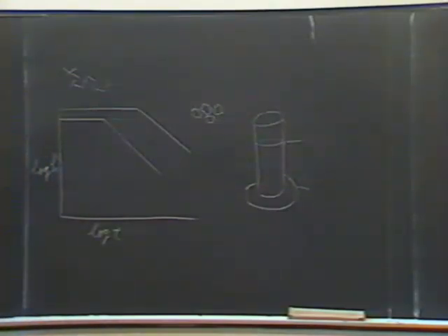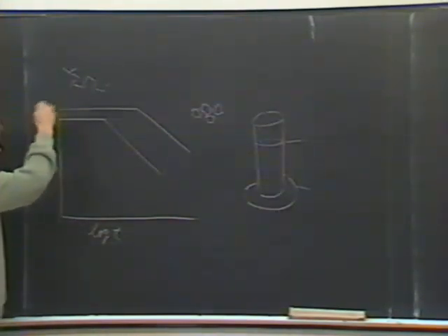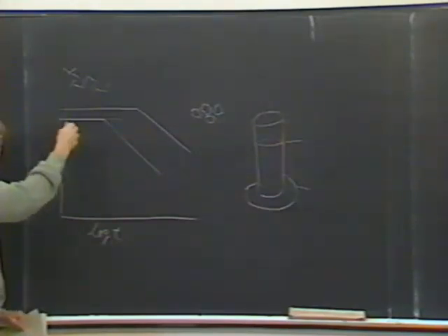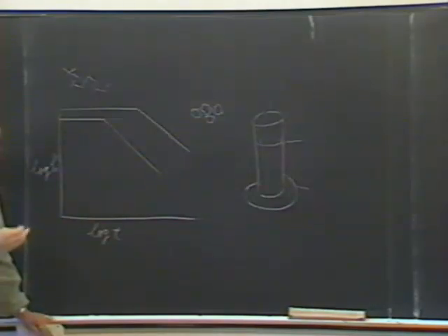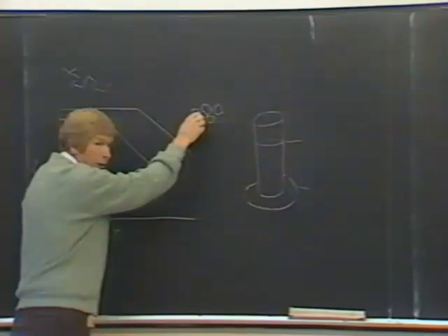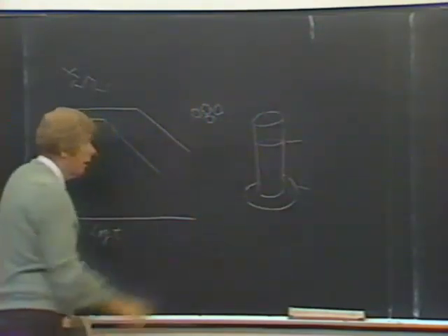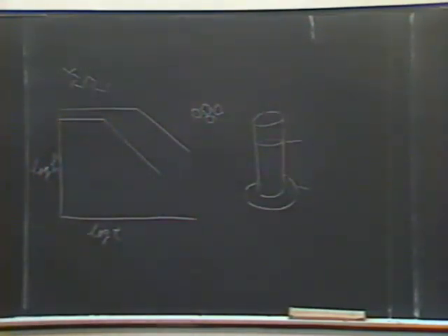The reason I describe this is that in slurries, for example, material dredged by a dredge and pumped through a pipe at high velocity, any kind of aggregate structure is broken up. We'll call it a slurry. It takes a while for the aggregates to form regions of greater density and lesser density that water can get through. Then it reverts to this kind of a system.